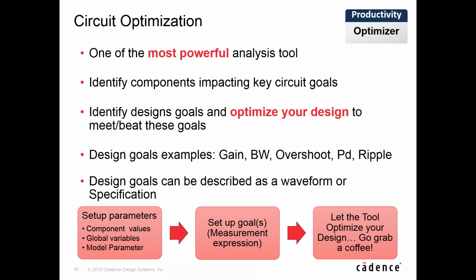And then there's circuit optimization. If you imagine that same circuit in your head that you're typically designing, instead of trying to figure out the best value of this feedback resistor, or the best value of this capacitor in the design, you can turn that on its head and tell the simulation engine, these are the components, I want you to vary their values, and I want to achieve this output. I want to have this voltage output, or this bandwidth output, or this noise value at the output.